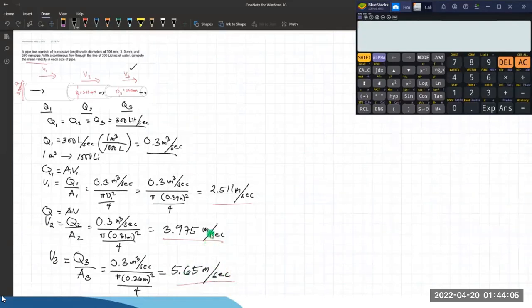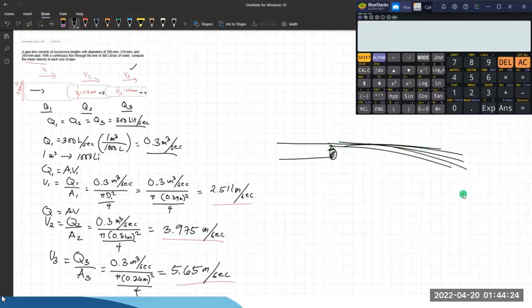So that principle is usually used on our garden hoses. On our garden hoses, usually we cover some part of the opening of the hose for us to have a stronger discharge. When we decrease the opening of the pipe, we have a smaller cross section or diameter, and it results in a greater velocity. So in this principle, we have already applied the conservation of mass. Okay?